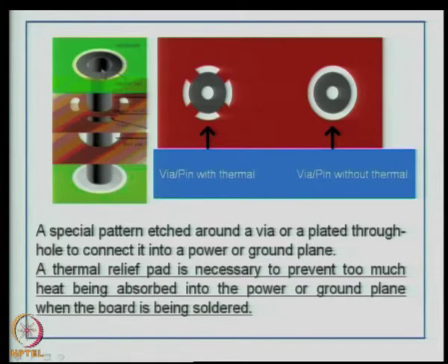See, imagine this is a through hole, a nicely drilled hole. This is the top layer, you can see. This is a green solder mask. This is the pad and this is the drill area. So, you can see the annular ring. Now, the hole passes through the second layer, and here you can see the thermal relief is provided. So, this is copper, no copper, copper, no copper.